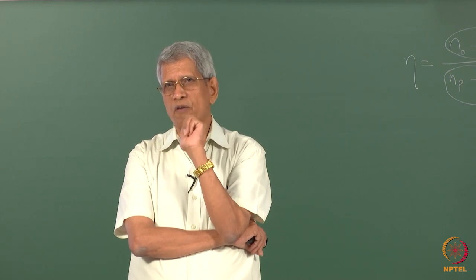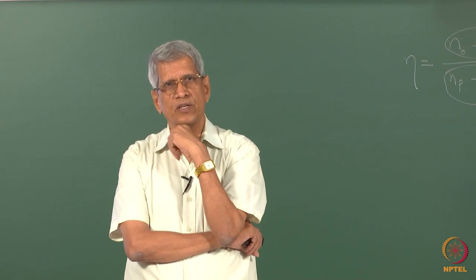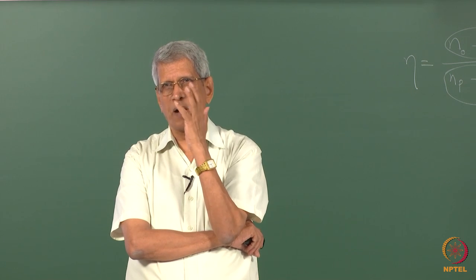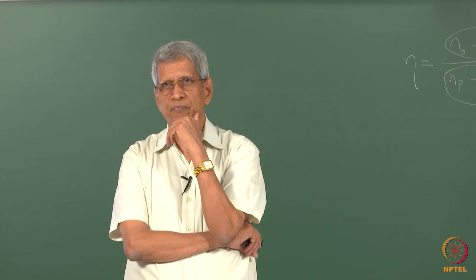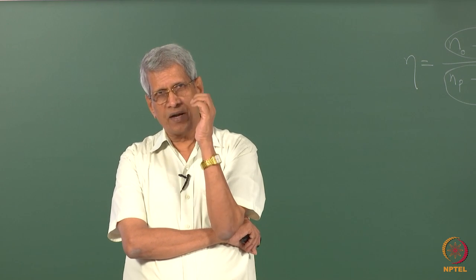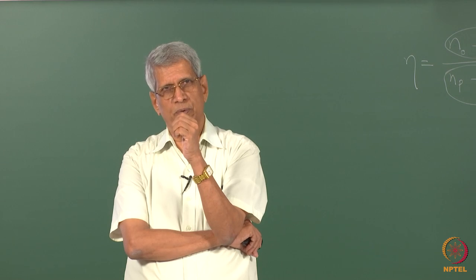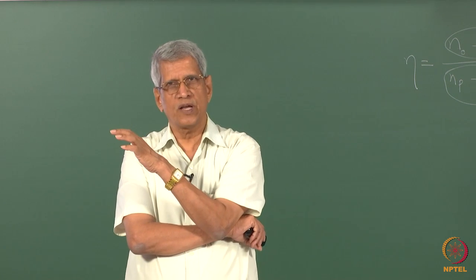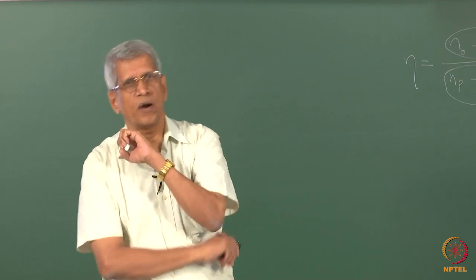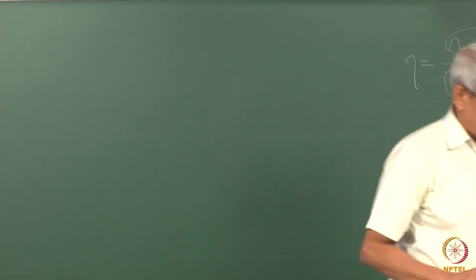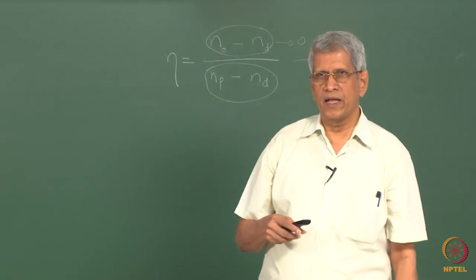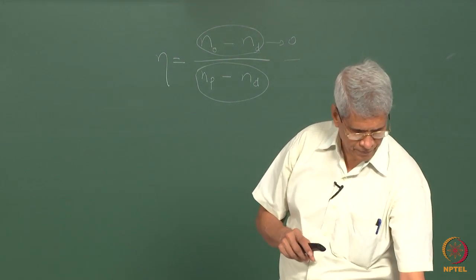But generally when we talk of the formation energy of a vacancy, it is a very small value, of the order of around 0.5 eV to 4 eV. That is because in that case, the atom which has been removed comes onto the surface, so only the net energy difference is what we have to consider as the formation energy. Because there is some energy loss and there is some energy gain also. The net difference is the energy which is required.